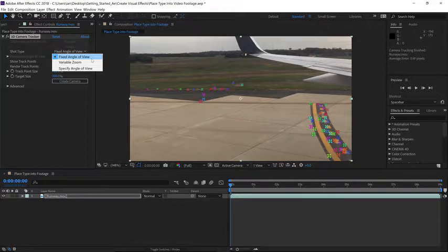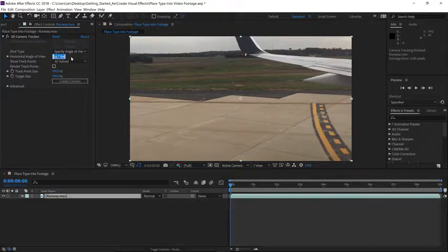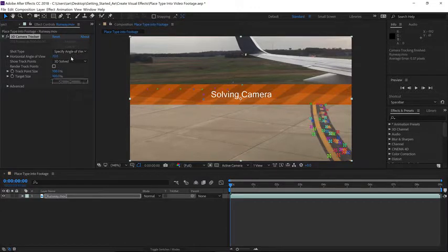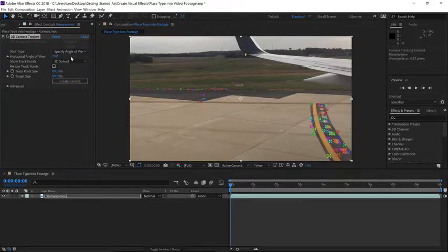So I went online and searched the angle of view for the model of camera that shot this footage. And it just so happens the angle of view, or the field of view, for my specific camera was 73 degrees. So I'll specify my angle of view, set it at 73 degrees and press Enter. Notice it doesn't have to reanalyze anything, it just recomputes the analysis.